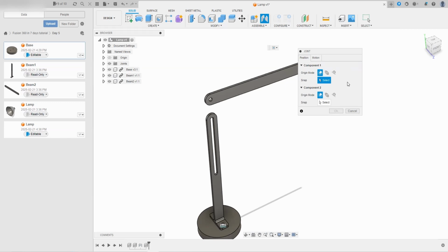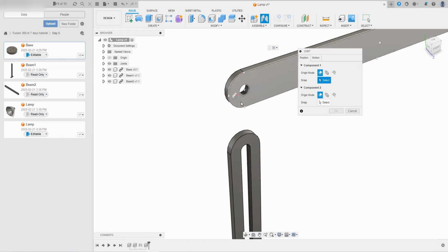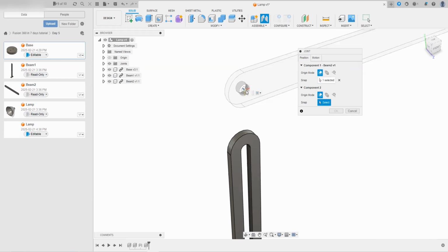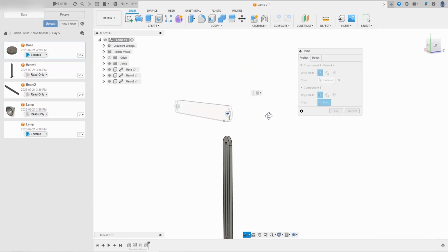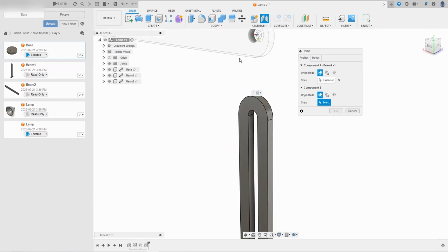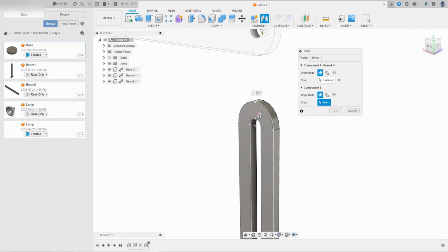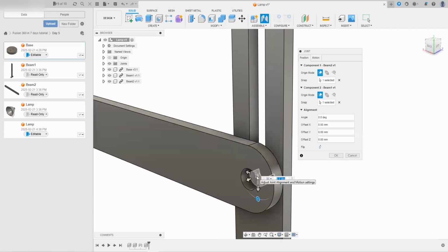So I will start my selection with an area on my second link. Like we did for the bolt holes, I'm going to select the center of the hole where I would like to put a screw. And we can see with the selection made, the selected object has gone transparent, and we can now make our second selection. For my second selection, I'm going to go ahead and choose the center point of the bottom arc. This will serve as the bottom position of my allowable motion.